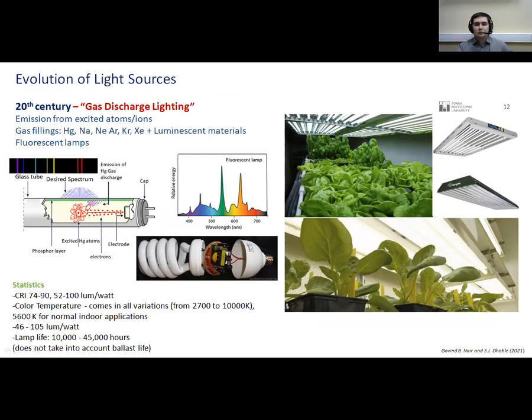Also, the luminous efficacies of the two designs differed significantly. The working principle for both types of fluorescent lamp is essentially the same. Both of them consist of an arced hollow glass tube. In this tube, we fill it with a mixture of mercury and argon vapors in a low pressure environment. The low pressure mercury vapor discharge lamp produces visible light due to the fluorescent or phosphor coating.